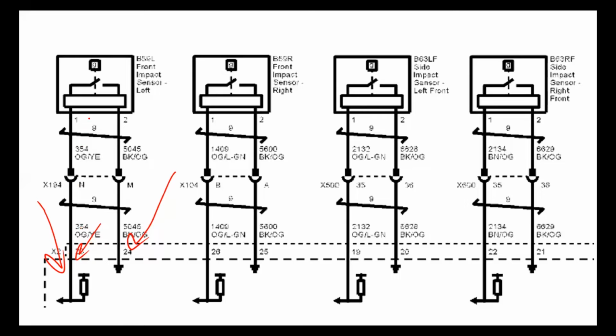Obviously, if there's a fault, we're going to see something. And then what I'm going to do is literally compare the signal from this guy to the signal from this guy. This guy's not sending codes, the right front. So we know that we can use that as kind of a baseline for what normal looks like. And then we can go over to the left front and see how close we are to normal.